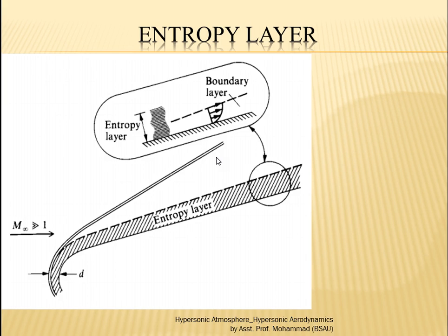The presence of the entropy layer causes an analytical problem in the standard boundary layer calculation on the surface, because there is no certain idea now about what the proper condition will be at the outer edge of the boundary layer.